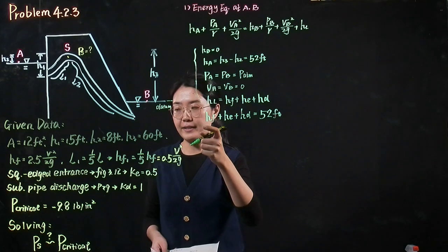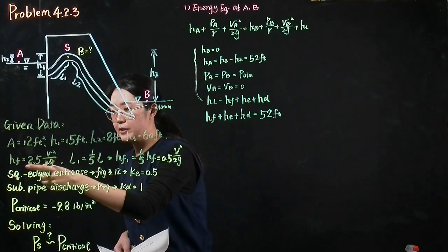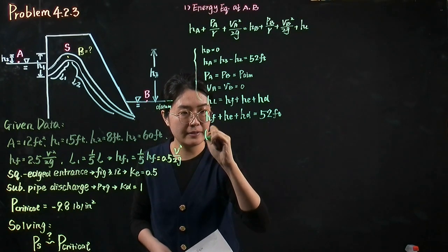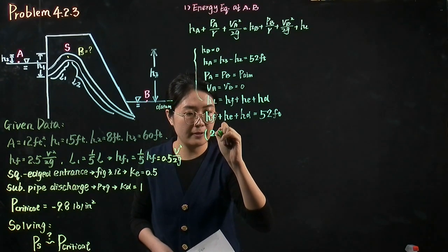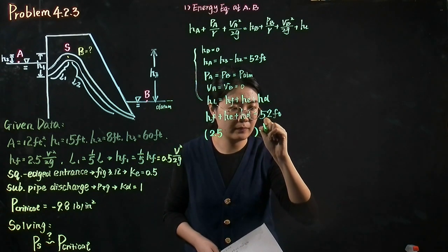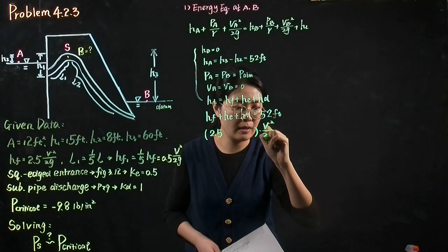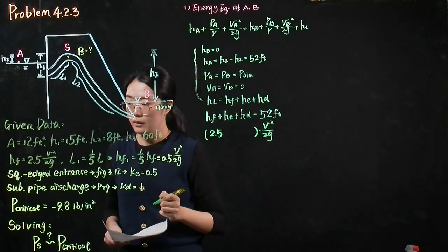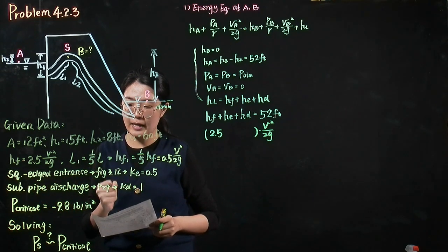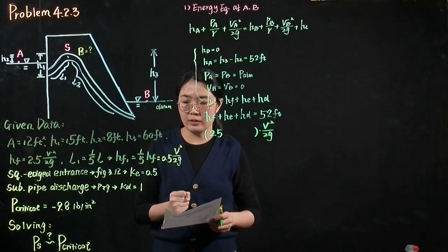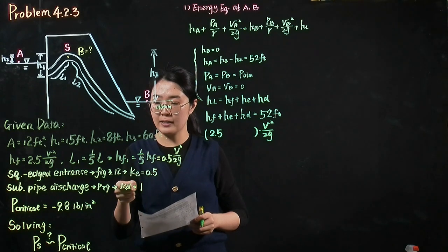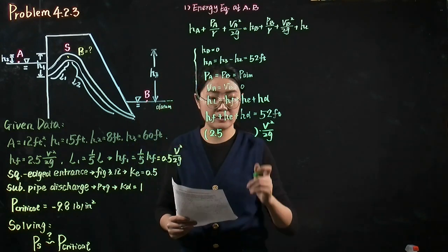Because the friction head is provided right over there, it equals 2.5 times the velocity head. Because there is a square-edged entrance, there is an entrance loss. The coefficient of the entrance loss equals 0.5, which can be found in figure 3.12.